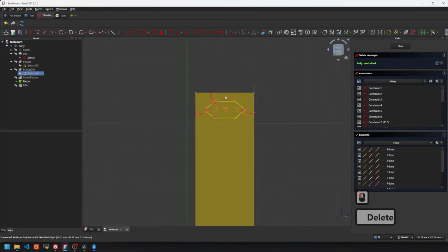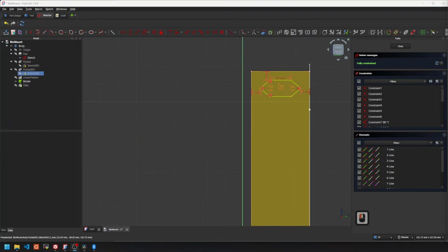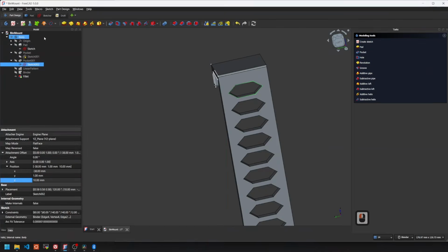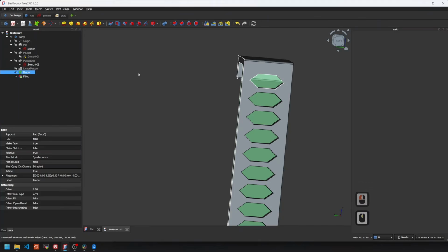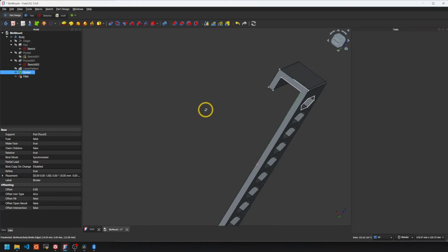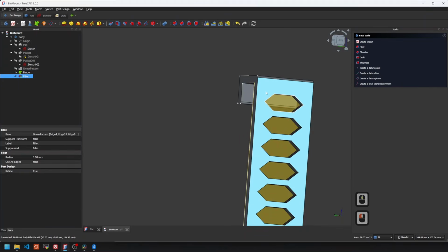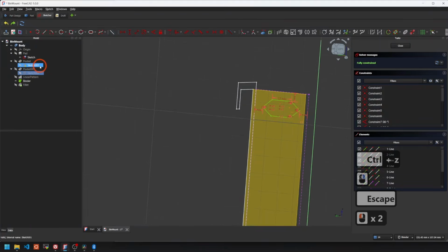And what is also new, you can see here this yellow face. This is a shape binder. So if we go back to the part design, it will simply close this. Then we can create here a shape binder. This is basically to create a reference from one sketch to another object or to another sketch. So I wanted to have my sketch referenced on this plane of the padding operation. So I was simply selecting that for the face, and then I clicked on this shape binder, and this will create a new object.